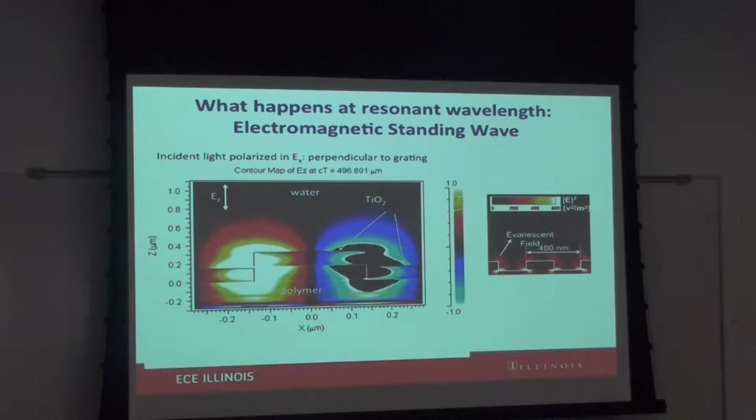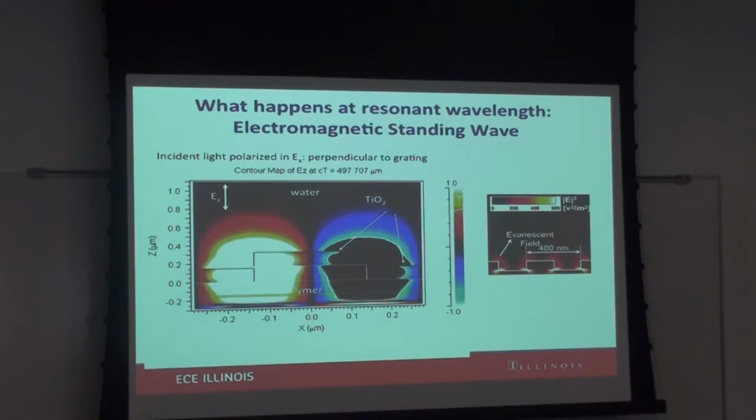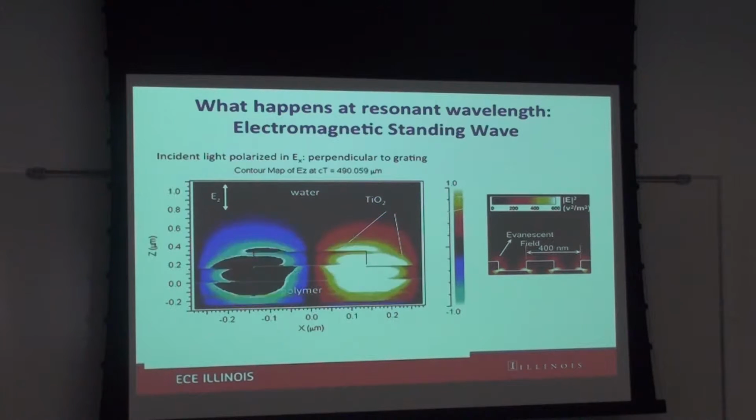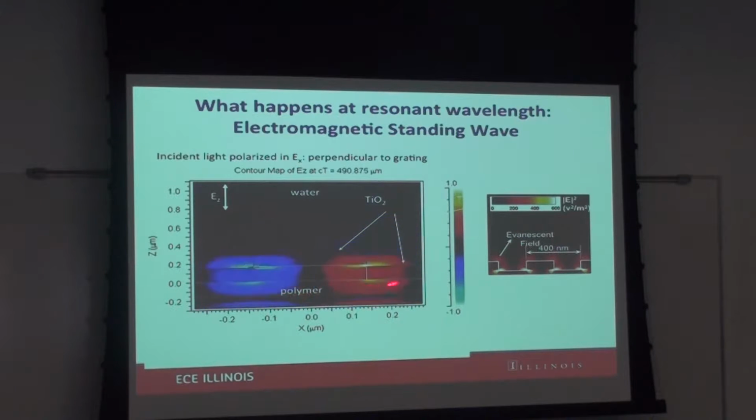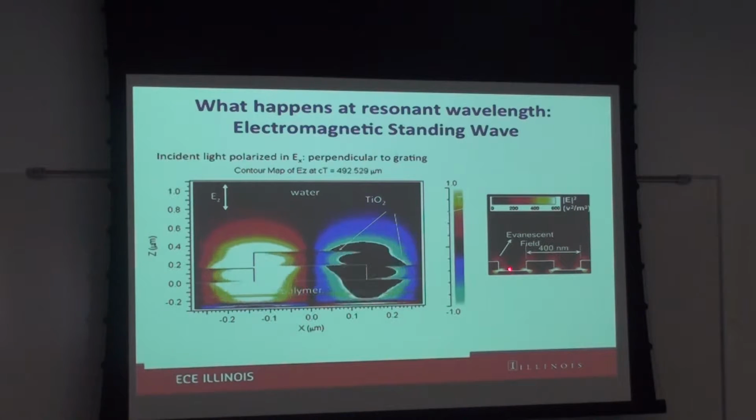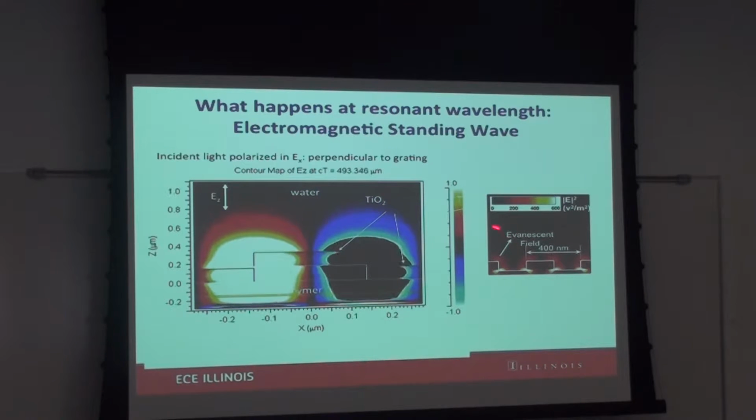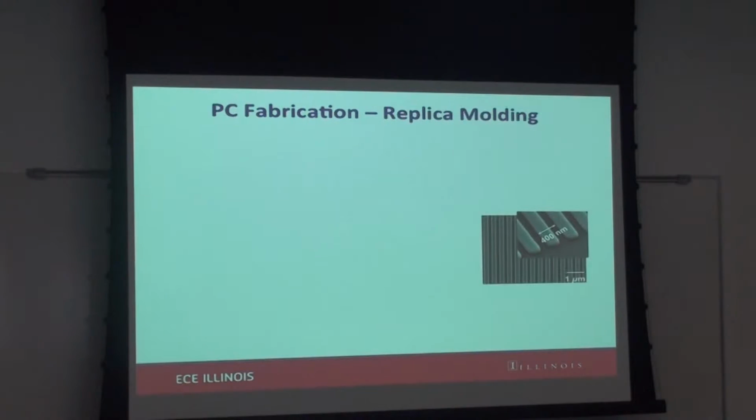And so what we've done now is to devise a way to take light from an LED or a laser, confine it to a surface, and amplify its electric field intensity. But that electric field intensity is confined to a couple hundred nanometers from the photonic crystal surface. If we were to take an average of this over many periods, we could think of this as what's called an evanescent field, where the electric field is near the surface, but is declining in intensity as you move upwards and away. If we illuminate the structure with an electric field magnitude of 1 volt per meter, we would see an electric field constrained to the surface with a value that can be much, much higher, even hundreds of times higher. This evanescent electric field is what we hope to use for interacting with biological stuff on a surface.